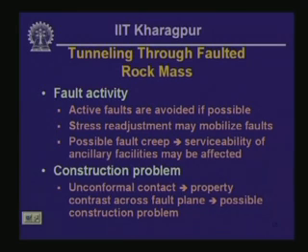The second aspect related to fault activity is that the stress readjustment because of the tunnel opening itself may mobilize faults. That is indeed the case in very deep underground mining operations, and it has been seen in many hard rock mines which can go a few kilometers, say 2 to 3 kilometers, below the earth's surface.